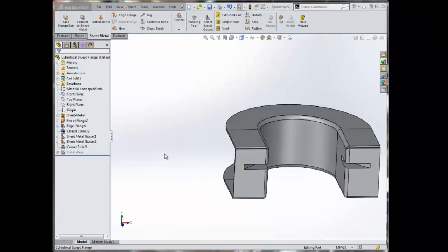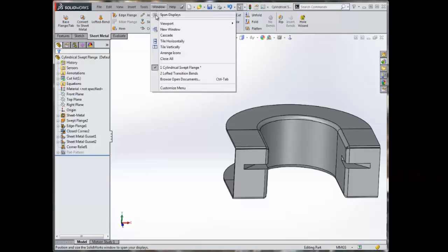Another scenario that greatly affects manufacturability is the use of lofted bends, another unique and powerful sheet metal design tool. And though SolidWorks has always enabled us to create this using formed methods, SolidWorks 2014 now provides an option to show this feature in a bend or transitional state.